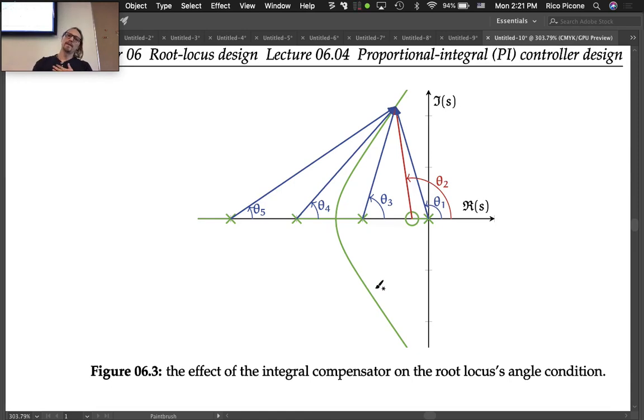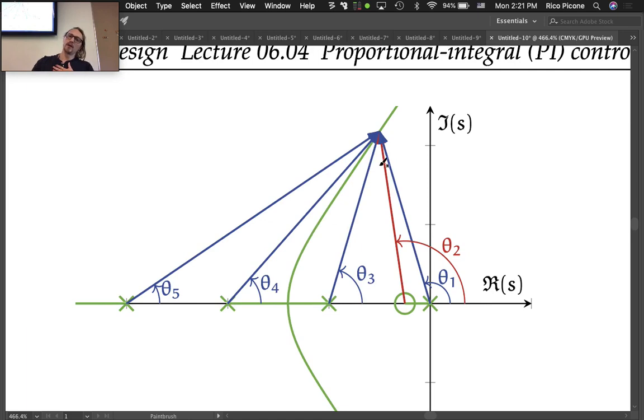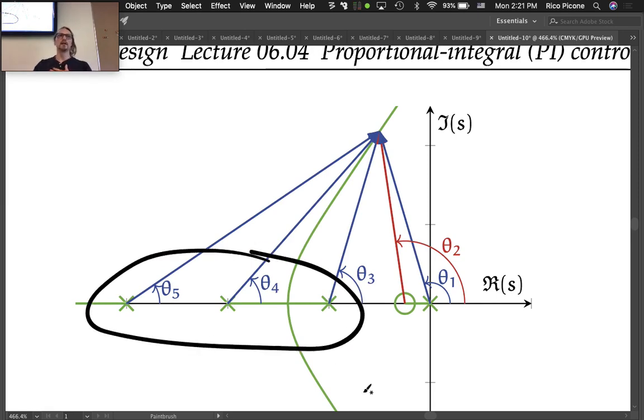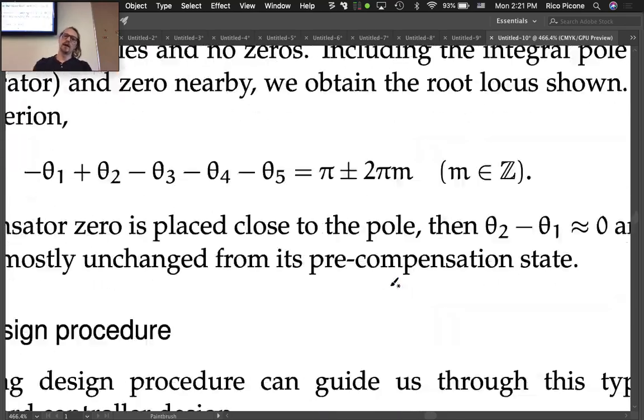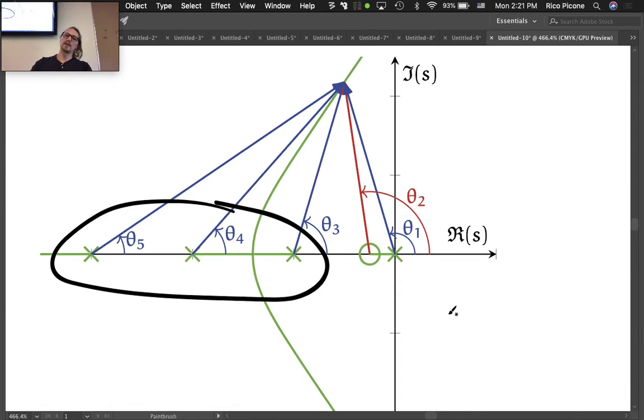Okay. So in this example, this is just an example, we have a root locus in green here, and we've got 3 poles that were in our original open loop transfer function. Okay, so those were already there, and they define the root locus, which has this shape here. So we're ignoring these two to start. So we have no locus, we have locus, no locus, locus. So one of the zeros is at infinity out to the left. One of them is at infinity out at this angle, 60 degrees, and then the other one's at negative 60 degrees. So we've got a root locus like that, and the angle criterion is met at every point on that root locus, right?